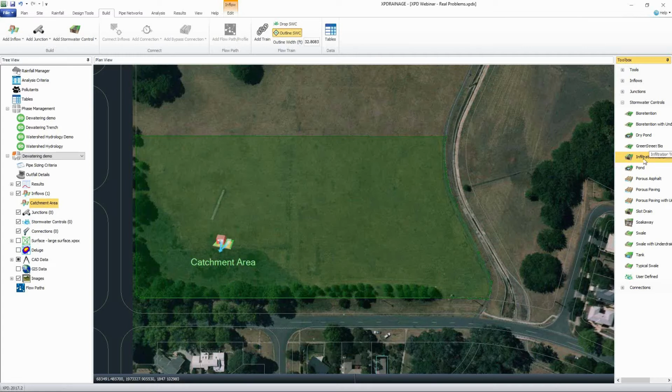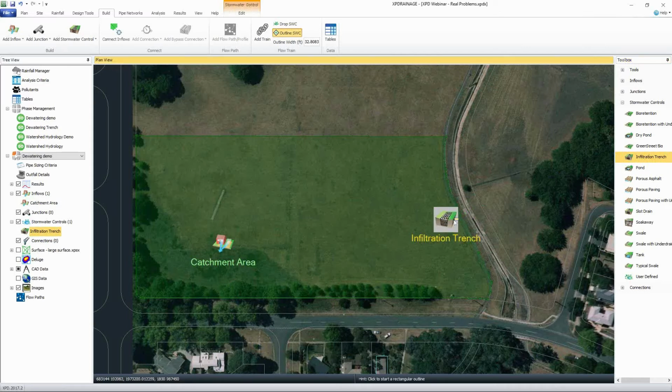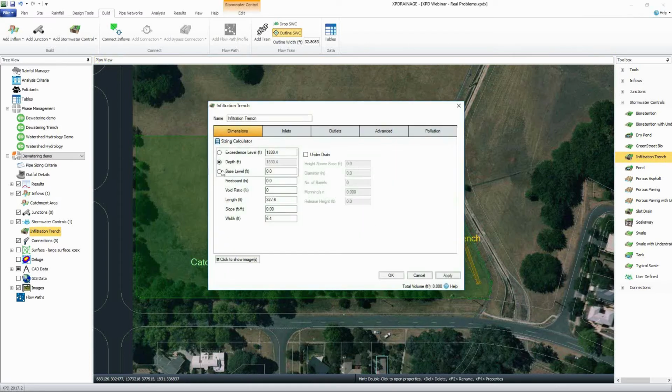One of these is the infiltration trench. I know my trench is going to be down here, and you'll see I'll add in this long, skinny trench, and I could twist that. Again, the layout is pretty important. So here's this trench. I might modify this further. Let me change the shape and make it really skinny. I only want it to be a few feet wide. In the real world, this is a very long edge of our site, but this facility might only be 4 or 5 feet wide and maybe 4 or 5 feet deep. So I'll say it's only maybe 4 feet deep.